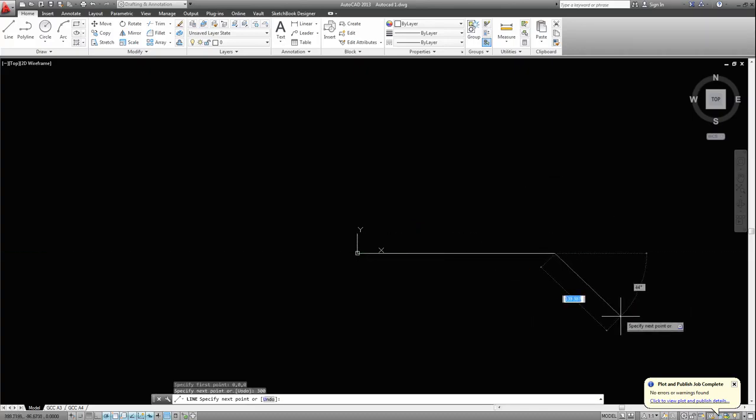There's my line, 300. Now, depending whether we want to go vertical, you see that it locks on vertical. We know that it's 90 degrees. What you've got to be careful with is if your mouse is too loose on the desk, if you haven't got a mouse pad, you can end up even typing and it makes the mouse bounce and you won't keep that angle right. To know that you're putting in the exact angle every time without any worries about the mouse, it's Shift at whatever length you want the line. I'll make it 250, Shift greater than 90.